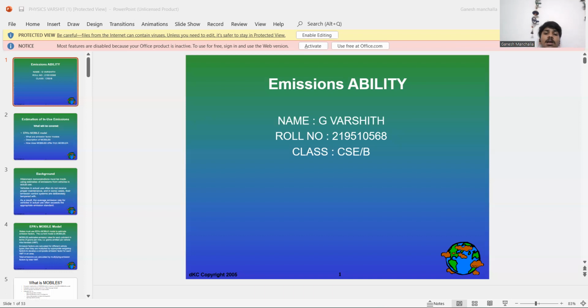Emission factors are calculated for different vehicle types. Then they are manipulated by appropriate weighting factors to develop a composite emission factor for each VMT in an area. Total emissions are calculated by multiplying the emission factor by total VMT.